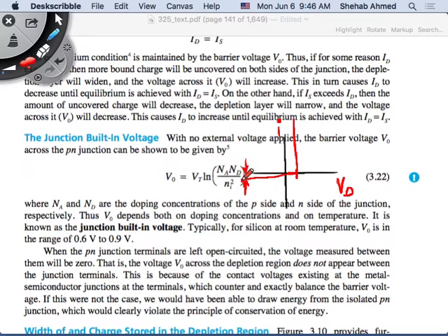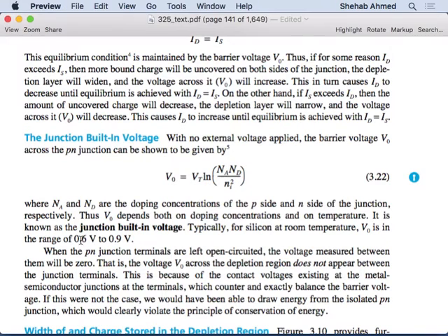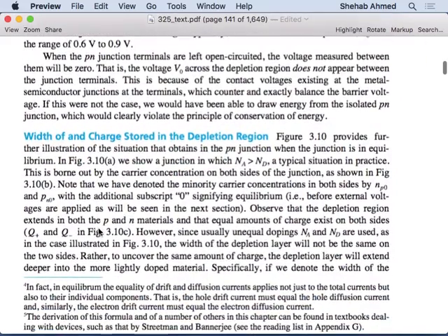This has a peak value here, I equals I_S, equals 10 to the minus 15 amperes, for example. Very, very small, right? But this is how a diode approximately works. The rest of the chapter spends a lot of time looking at more details of how this diode is operating, but this is simply how it works, okay? And we see this application of this 0.6 to 0.9 volts, right? And then,